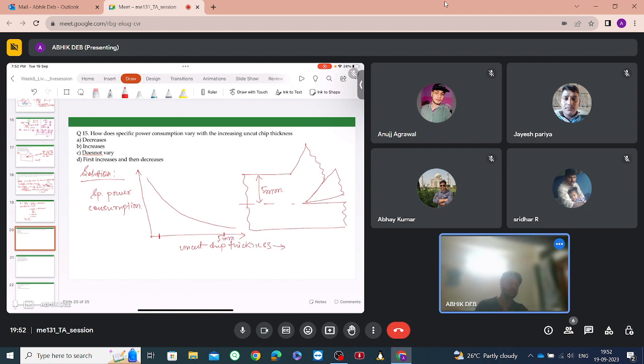Now in this case, this is a very low value, say 1 mm. Instead of 5 mm, if we take a cut like this, 1 mm, then to achieve a depth of 5 mm, how many cuts will we have to make? 5.